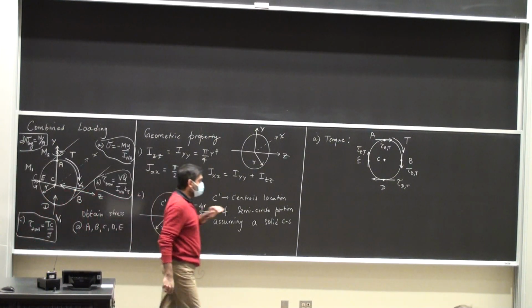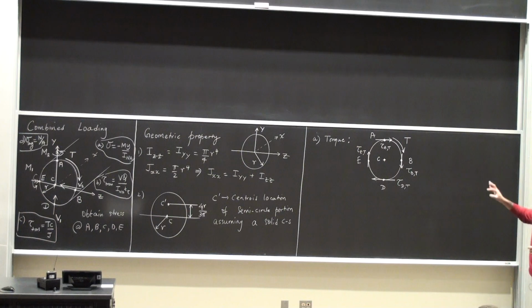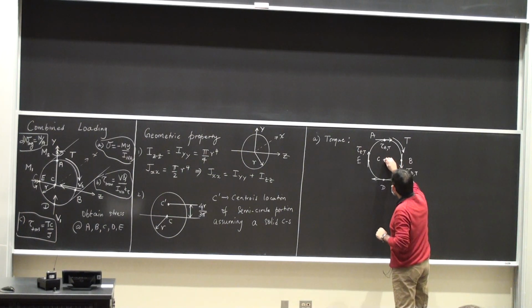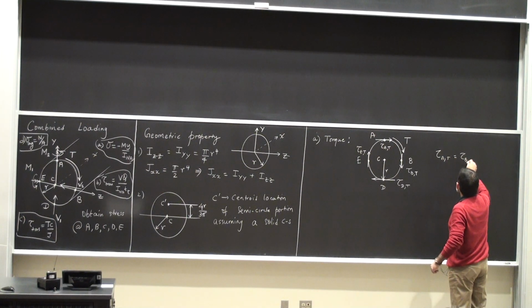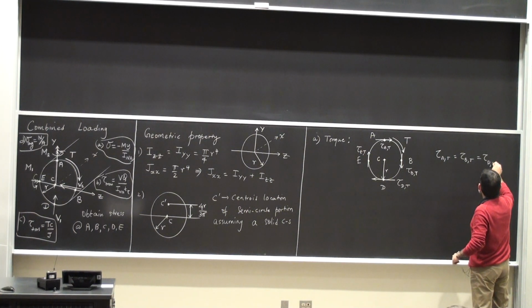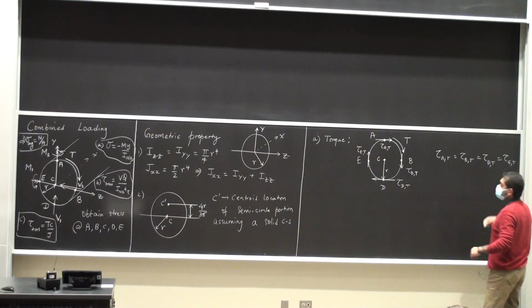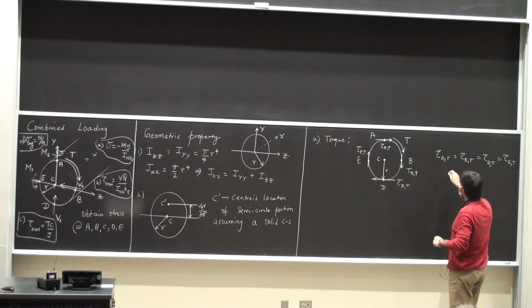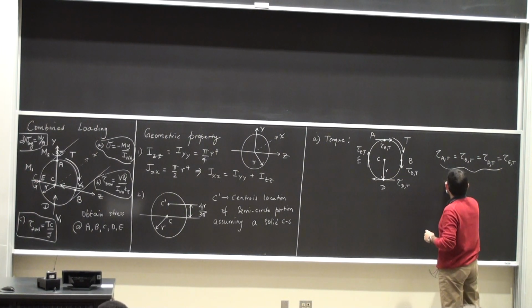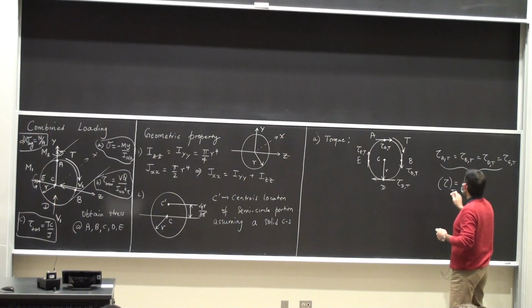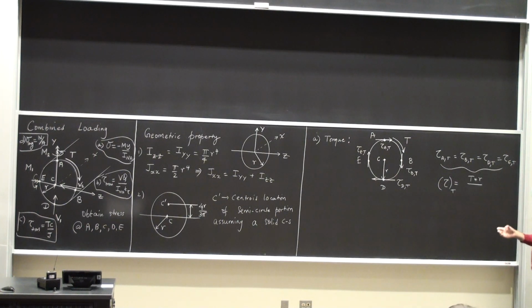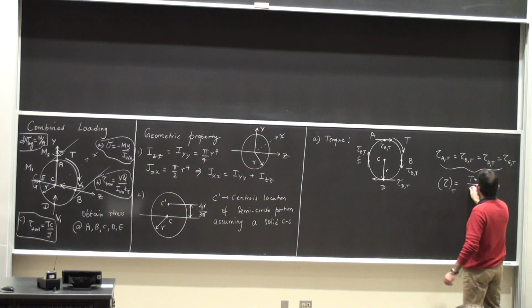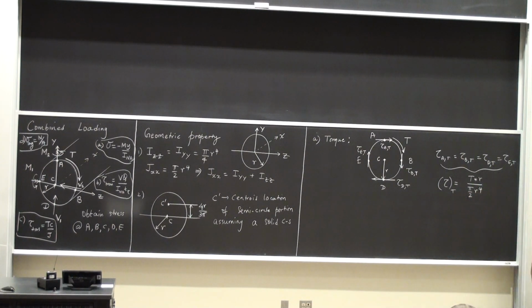Okay? Alright, these shear stresses are all the same value, so I will not belabor that point. They are all equal to the following. Radius is R. So tau, the magnitudes are the same, and I do the calculations. These are all due to the torque applied. These are equal to T times R by J, it's a solid cross section, so pi by 2 R to the power 4. And I can do a little bit of simplification.